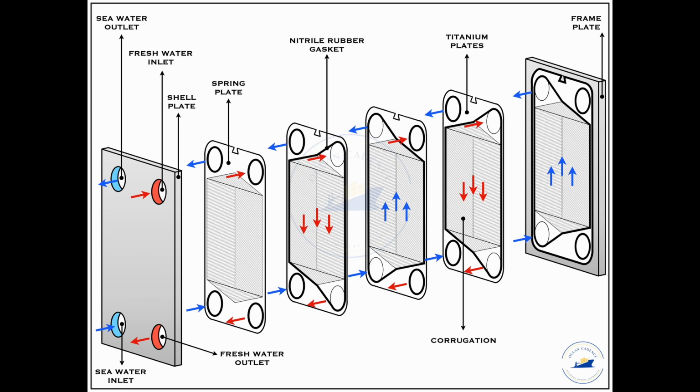that the arrangement of the plates can get distorted. So what we do is, by using efficient gaskets, good quality gaskets and new gaskets, we allow the compression to occur mostly on the gasket surface instead of the load going onto the plates, and by doing so the gasket will seat perfectly on every plate surface and thereby provide efficient sealing and no fluid loss during the heat exchange process.